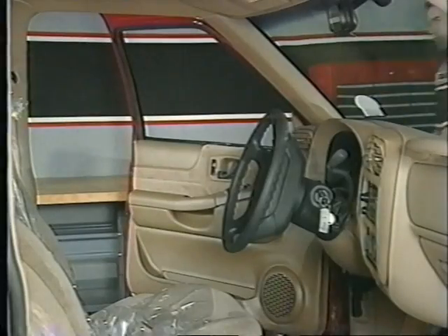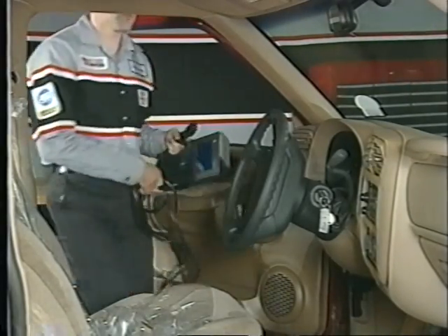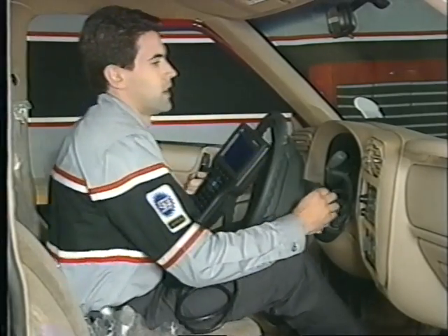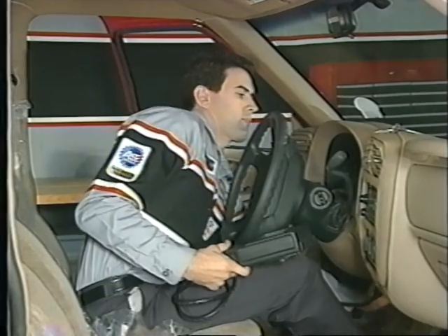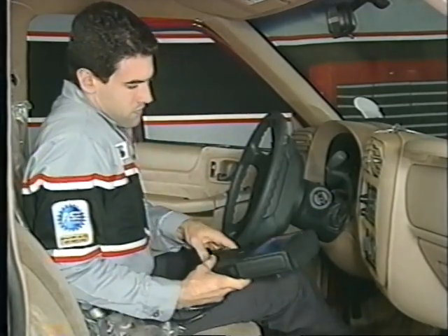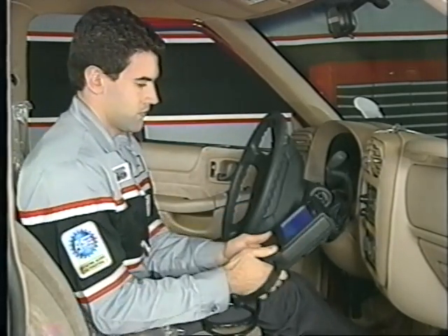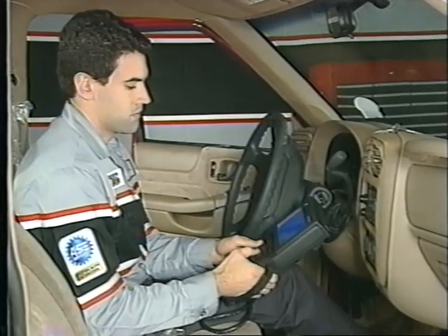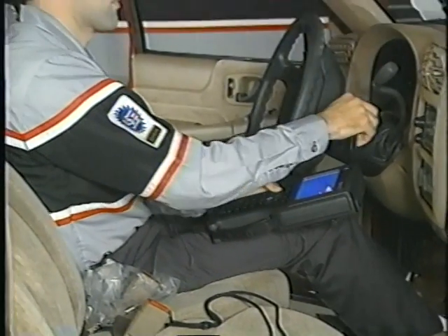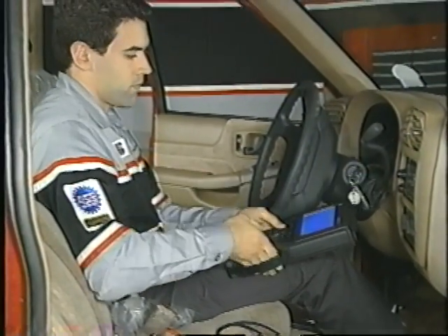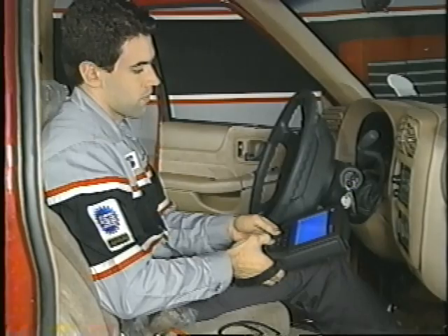Complete your repair by checking that all clips are properly installed and that the wiring is not chafing or contacting any hot parts. Then you can confirm that your repair was done properly using your Tech 2. Start with the ignition turned off. Taking the key out is a good way to be sure. Hook up your Tech 2 and program it as far as you can without having the ignition on. Now you have 2 minutes to complete the procedure once you turn on the ignition. So you should quickly finish programming your Tech 2 to bring up the data for the oxygen sensor.